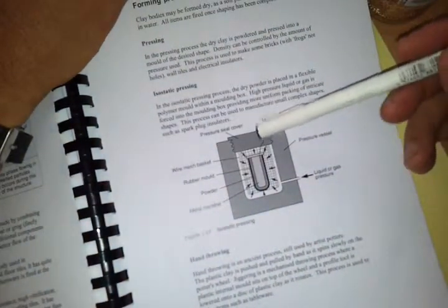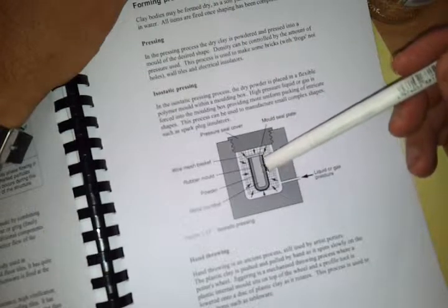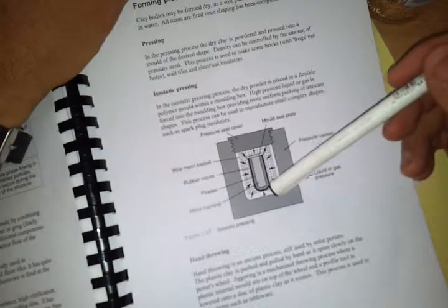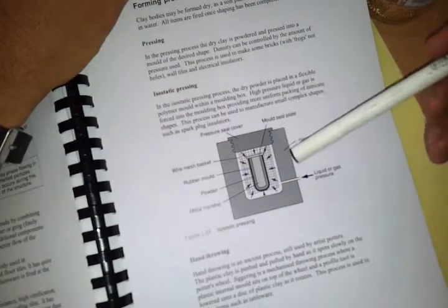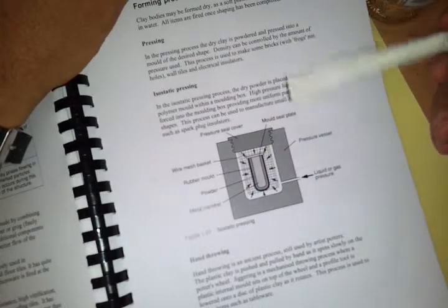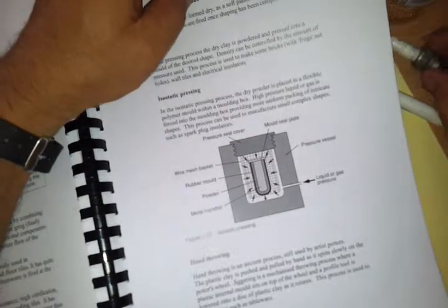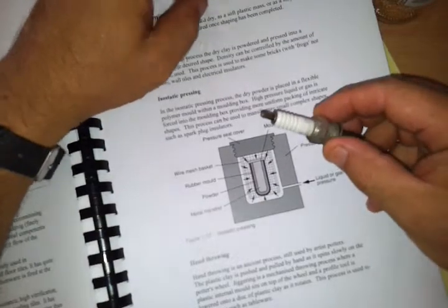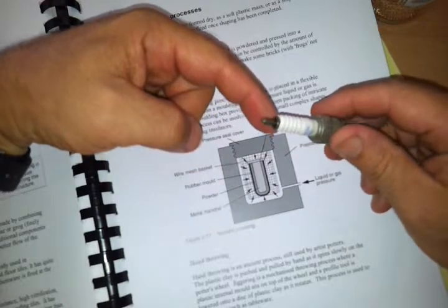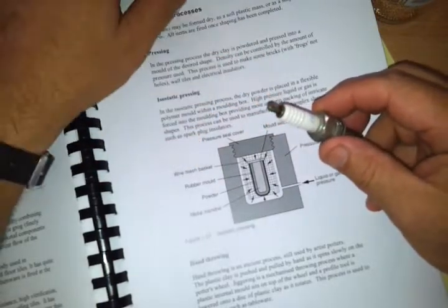It involves putting some metal powder into a mould and using pressure from a gas or liquid to form that shape, and under heat and pressure the ceramic is formed. It's not so much the thing that you need to be very aware of, but just to know that it is used for some complex shapes. For example, this spark plug insulator would have been made through isostatic pressing, very high temperatures and pressures.